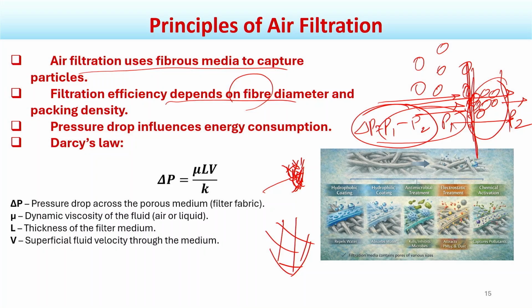Okay. That is why, for a clean room, only one layer of filtration will not work; we need multiple layers of filtration. First there will be a coarse filter where air can flow at high speed, then gradually a very fine filter where we need fine particulate matter to be arrested, and that will give you a very low speed, that we need, a very lower speed.